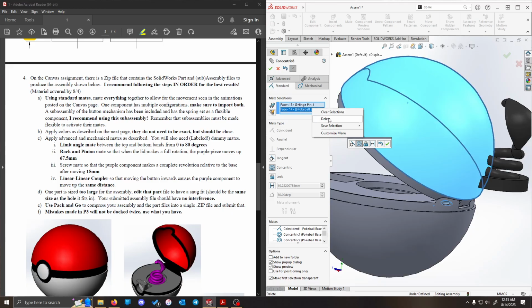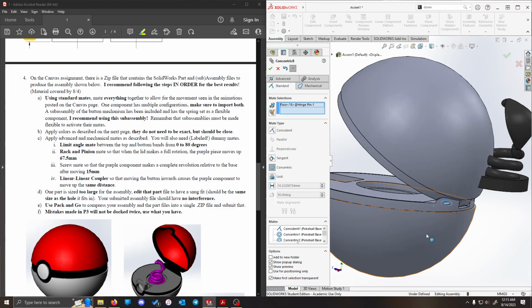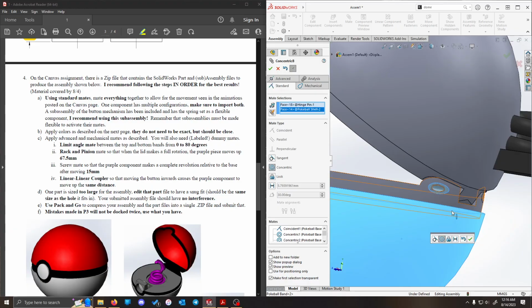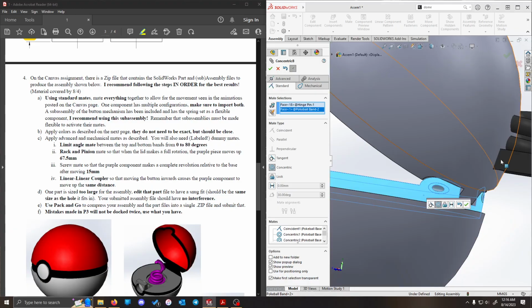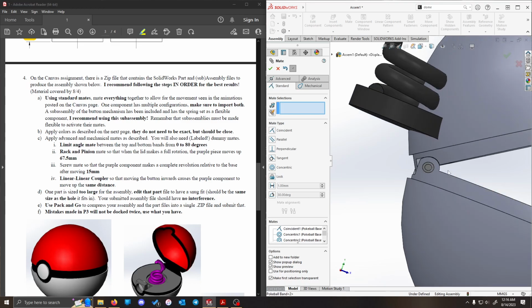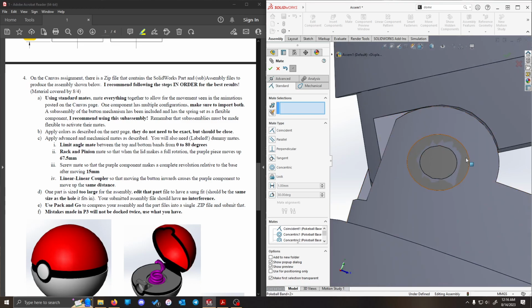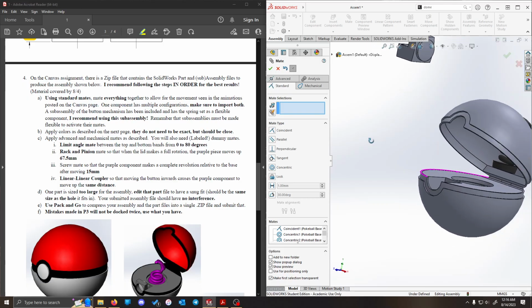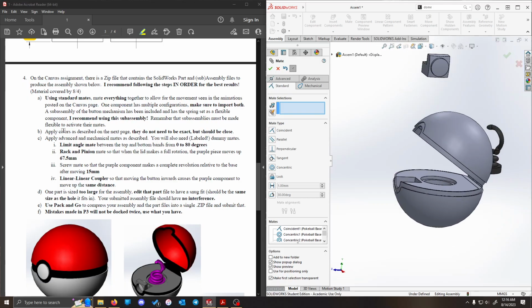That was one of the two other spherical surfaces that would not work the way that we want. So since the hinge pin is based off of this bit, this one actually makes the most sense. So we'll select that surface there, and the concentrics will keep the pin snugly on the inside of the object. We can see a little bit of glitching here, where the two models are overlapping with each other. That may or may not be a problem that we're going to solve later on in the process.